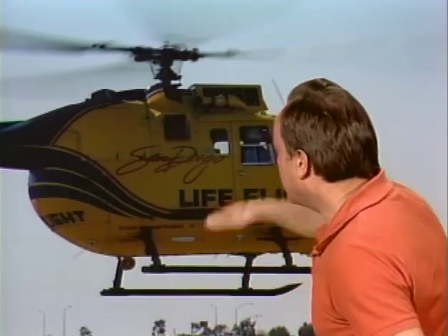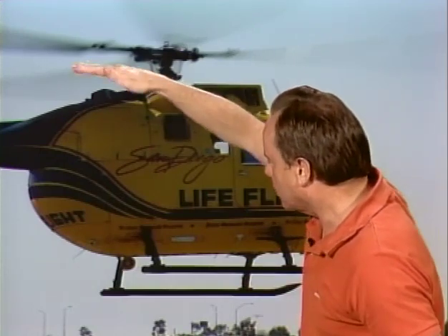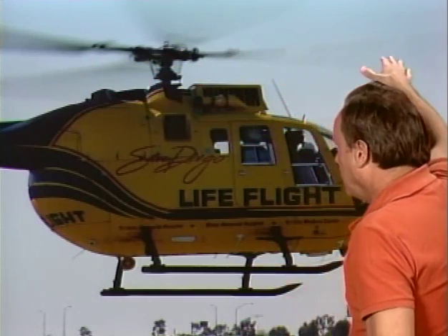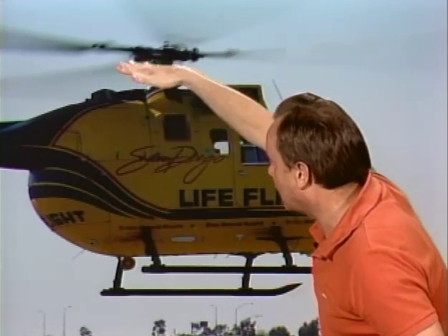Now, let's assume you're flying along. They want you to know, of course, that there is a downwash effect as the helicopter is flying along, and there is a greater downwash effect through the aft part of the main rotor disc. The reason for that is that the air in front goes down and the helicopter flies through that downwash, and it gets greater at the aft part because the helicopter is moving into that air. Now, what is that effect called? They ask you on the test, and the answer is that effect is called transverse flow effect.